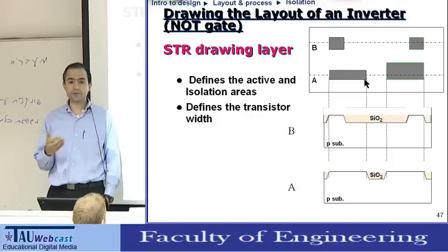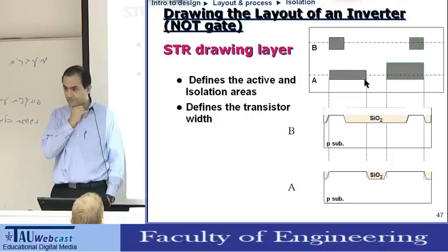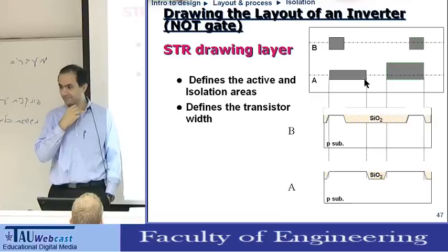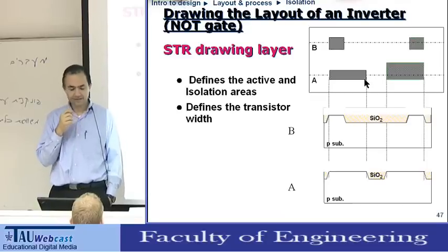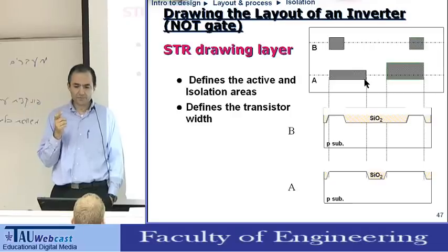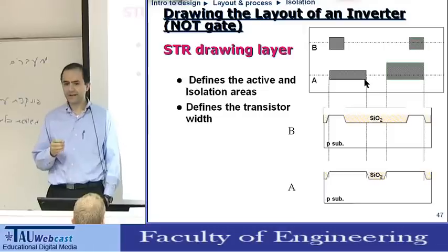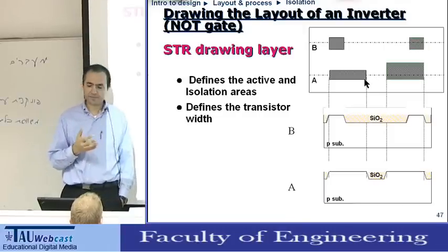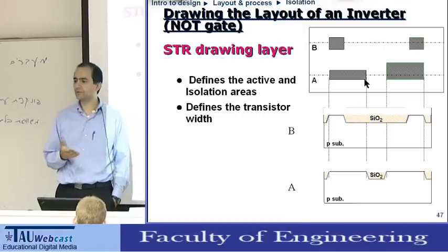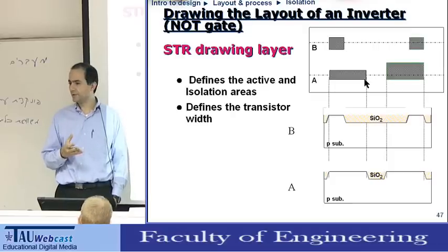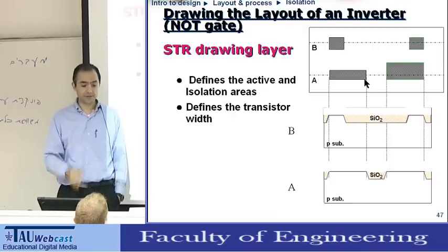So which tool will we choose? The cheapest one. Which would be the cheapest one? The I-line, the 365, thank you. So we will choose the cheapest tool, and the cheapest tool would be the one with the worst resolution. So for each layer we will choose the worst resolution that will still work.